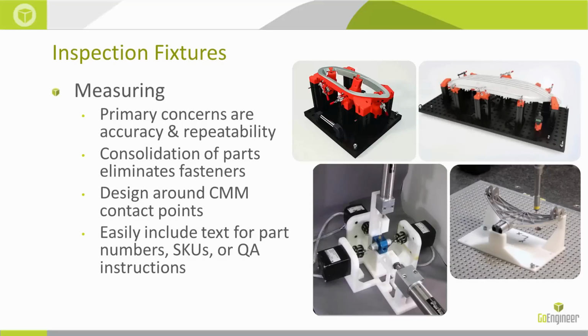All right, measuring. So this is still the Q&A, guys or gals. So instead of putting a part in the fixture and testing it or breaking it or putting it in some sort of functional situation, here we're just measuring it. All right, so this is basically a CMM process, but it could also be other measuring types. And your primary concerns are going to be accuracy and repeatability.